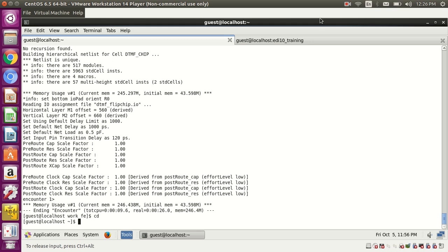So it has to go from RTL to synthesis to PD, and then again to RTL, because some flops may sit further apart and cannot meet timing, so we ask them to add registers. They need to change the clock cycles: if we add one clock cycle, there are 10 parallel paths, 10 registers with start points and end points, performing certain logic. Suppose in those 10, only one path is not meeting; it cannot meet in one cycle.